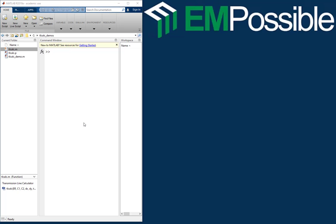Hello and welcome to this video in which I will explain how to build a coaxial transmission line in MATLAB and how to analyze it and visualize the fields using the tlcalc function. I will assume that you are already familiar with building geometries in data arrays, you are familiar with transmission line theory, and also that you watched the first MATLAB session video in which you analyze a microstrip transmission line. With that said, let's begin.